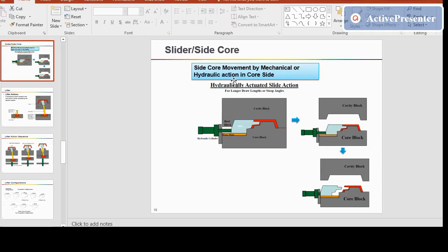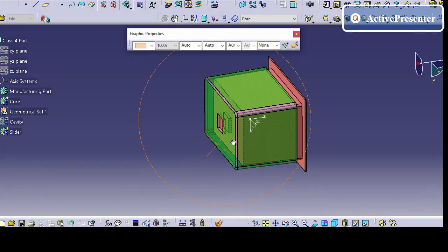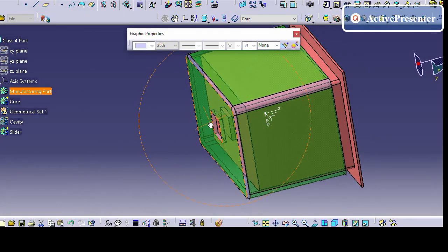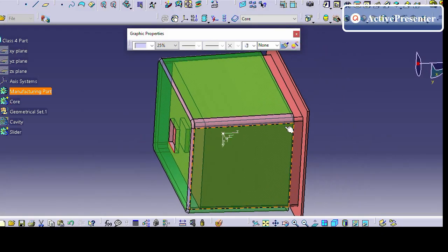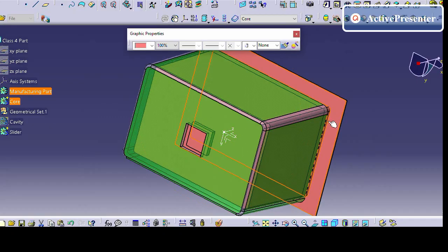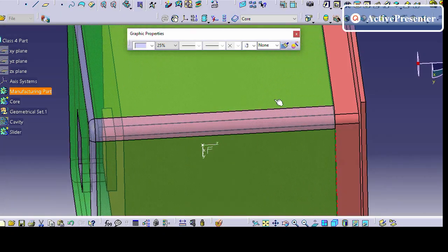B surface, anyhow, we will do the replicate of A surface, but for this closing surface, C surface, we need to consider this tooling direction. Only there we will have this parting line. Here you will have a separate parting line, because here what will meet? Your core, your part and your cavity. Here you will have the separate parting line, and here you will have the separate parting line. This is what your parting line, core, cavity.